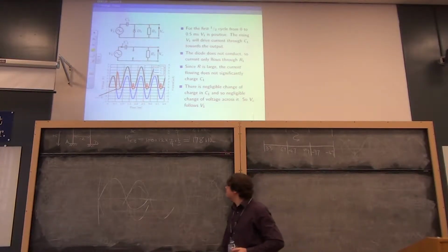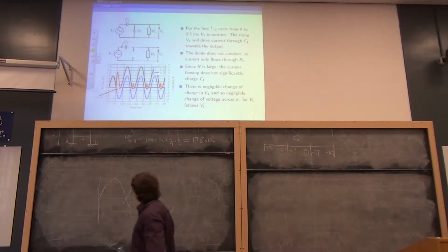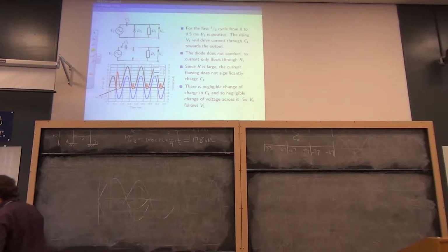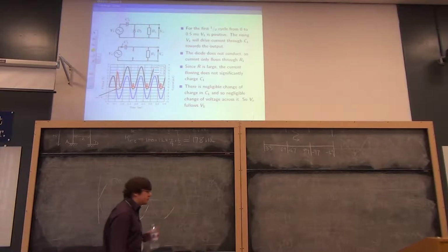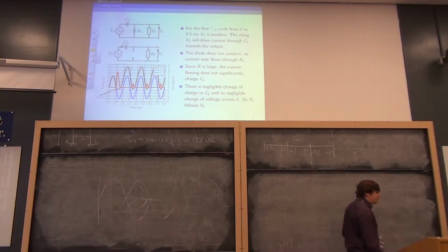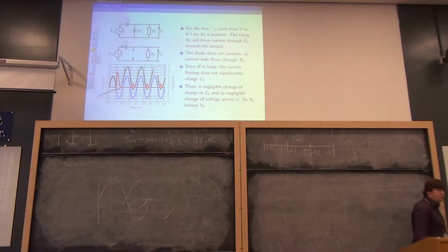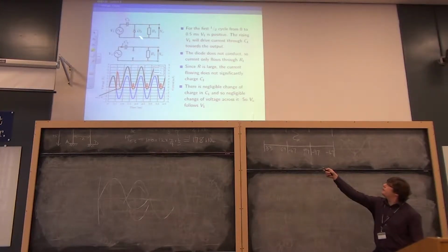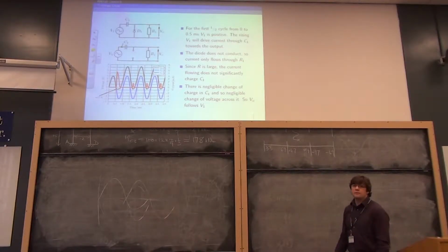We have the capacitor C1, the diode D1, and the resistor R1. The thing is that electronic components are heavily unionized, and I can only afford a few of them. And we have two situations. We've got the diode conducting, which I've got as the top situation, and it would be perfectly acceptable to replace D1 with a 0.7 volt source. I just haven't in the diagram. So you could make that a 0.7 volt voltage source if you wished. That would be fine.